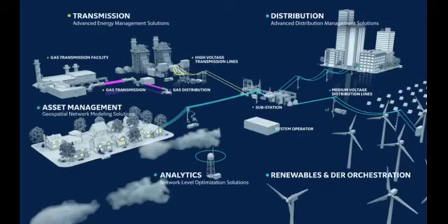Voltage control and regulation. FACTS controllers such as static VAR compensators, SVCs, and static synchronous compensators, STATCOMs, are used to regulate voltage levels in power systems. They can maintain the desired voltage profiles, compensate for voltage fluctuations, and stabilize the grid during voltage sags or swells.